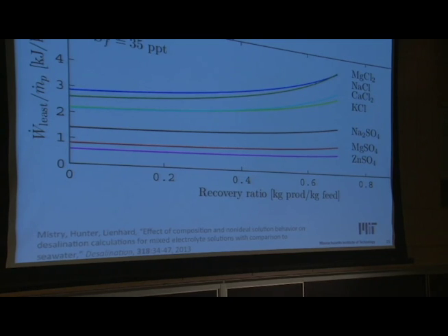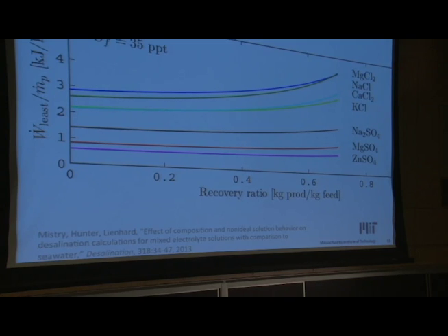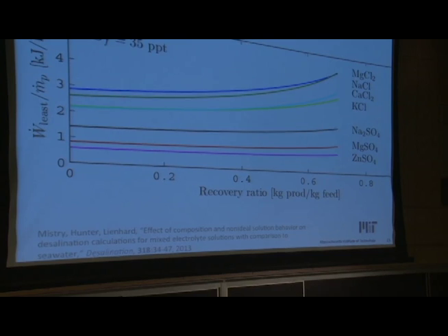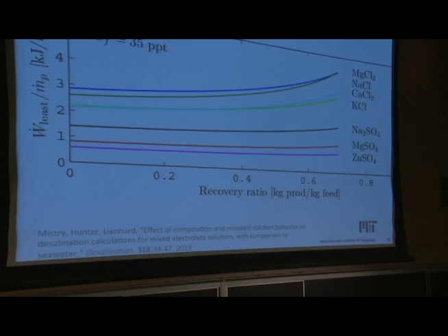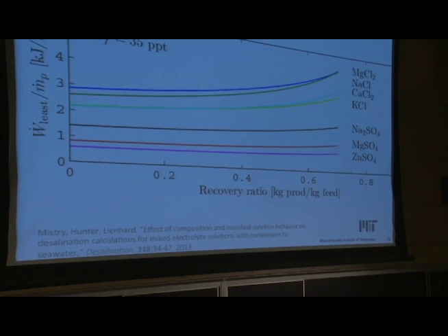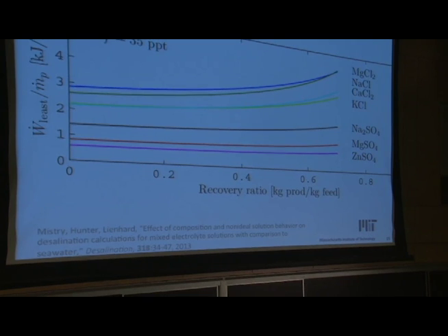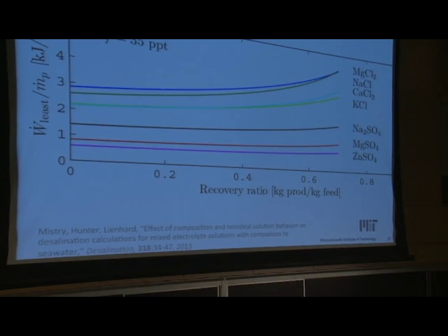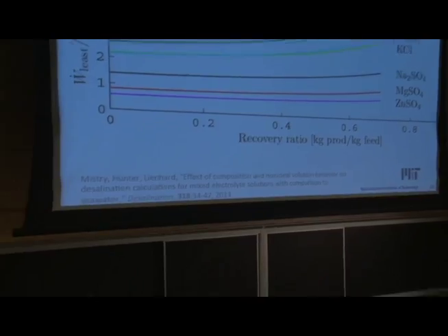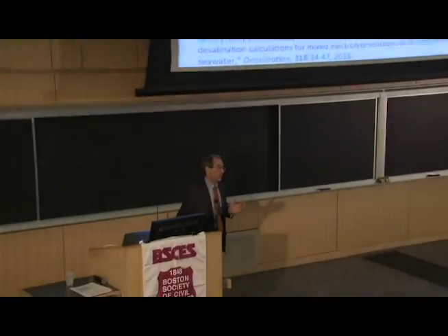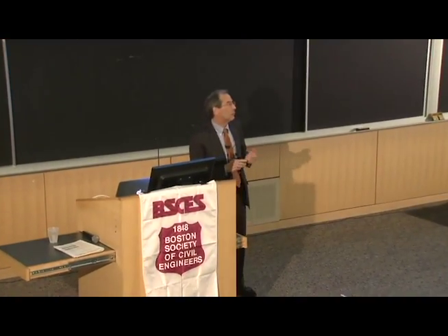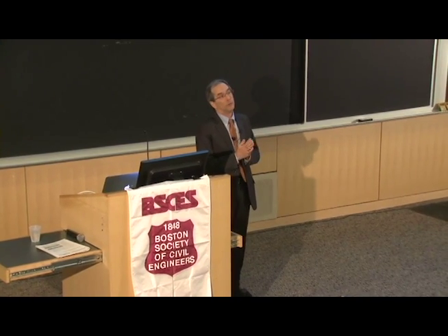It turns out that seawater around the world has more or less the same proportions of dissolved ions. It can be saltier or less salty depending on rates of evaporation and rates of freshwater inflow from land. But in general, you have about 80% sodium chloride in similar proportions for calcium, sulfate, carbonate, some other common ions. If you're dealing with groundwater, the compositions are different and the proportions are different. So you have to be a little careful in just thinking you have diluted seawater.